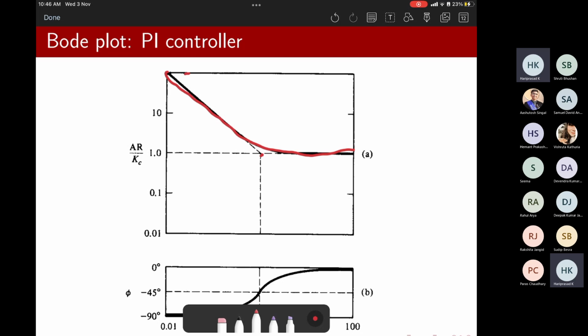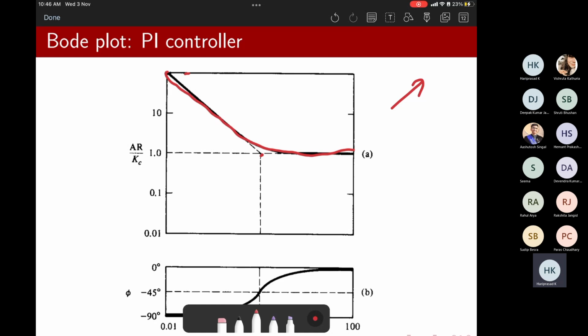So this is a slight inference. I can tell you some take home message out of it. What is a controller? A controller is technically an inverse of the model. You see IMC, what we are doing is inverting the model. Are you getting my point? Whatever the model tries to do, the controller tries to suppress that. The model behaves mischievously, but the controller would try to tighten it. Agreed or not agreed?